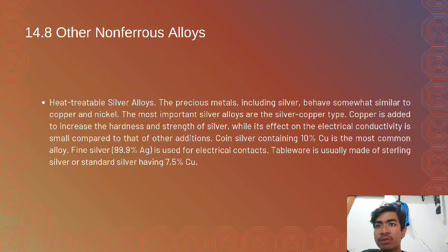The only commercial application of constitutional data is in the annealing of this alloy at temperatures as high as 600 to 700 degrees Celsius, then rapidly cooling to secure a soft condition for subsequent cold working. The only other silver-based alloys that have been found amenable to hardening are the silver iridium type. Heat treatable gold alloys.